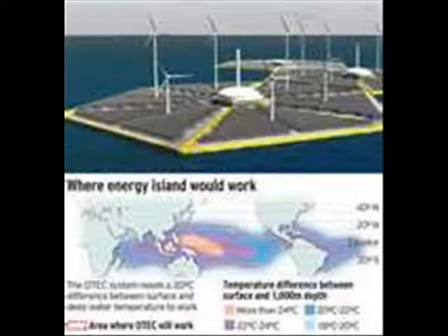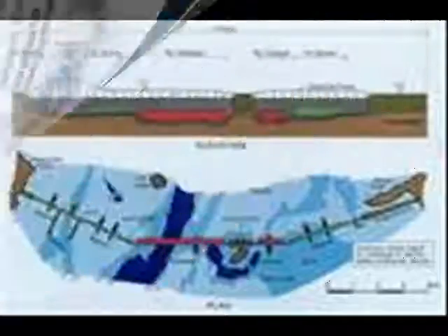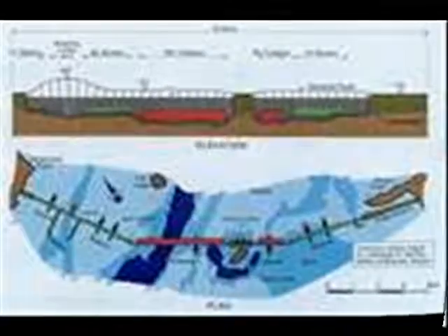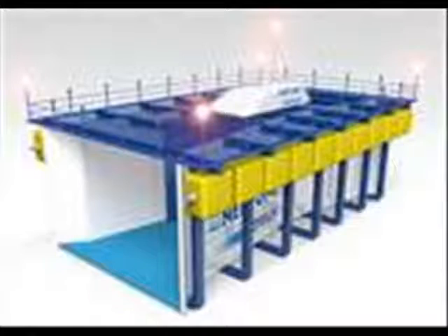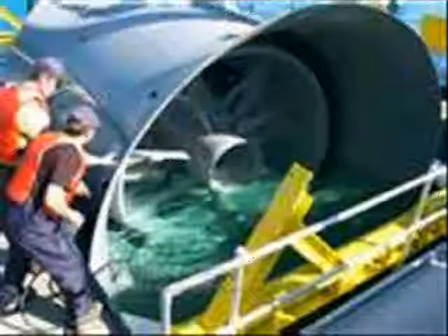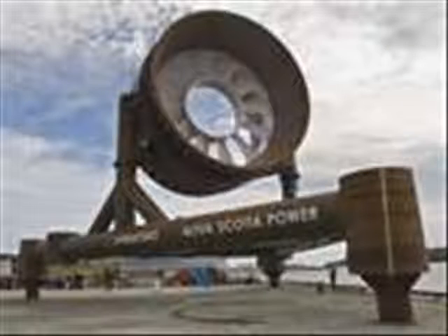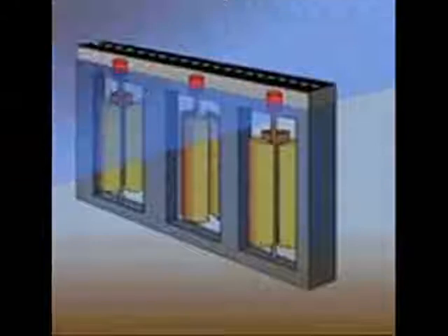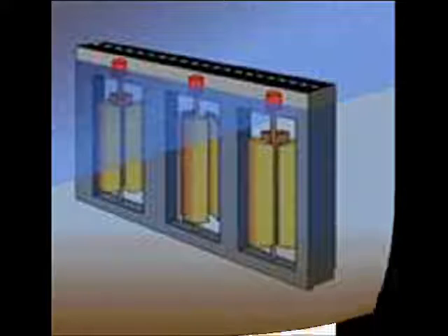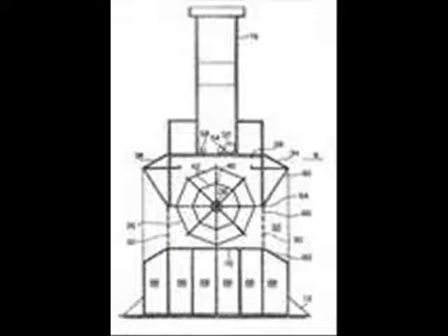The smaller the site's Gibrat ratio, the more desirable the site. Examples of Gibrat ratios are La Rance at 0.36, Severn at 0.87, and Passamaquoddy in the Bay of Fundy at 0.92. Offshore tidal power generators use familiar and reliable low-head hydroelectric generating equipment, conventional marine construction techniques, and standard power transmission methods. The placement of the impoundments offshore, rather than using the conventional barrage approach, eliminates environmental and economic problems that have prevented the deployment of commercial-scale tidal power plants.